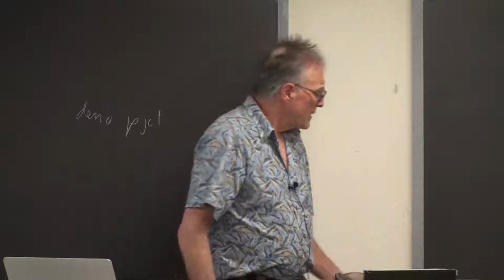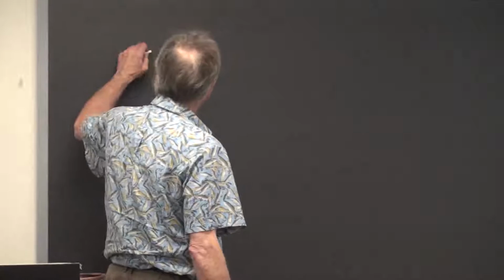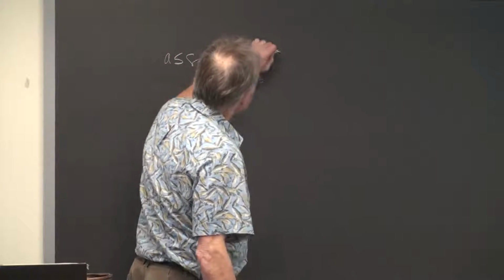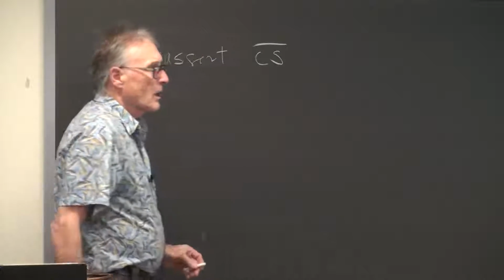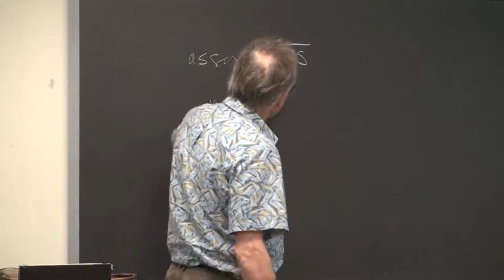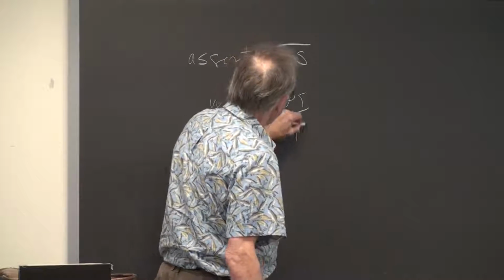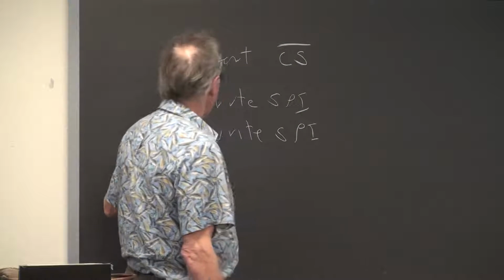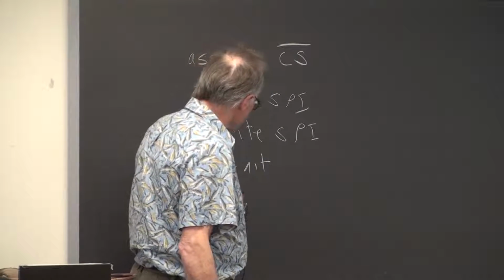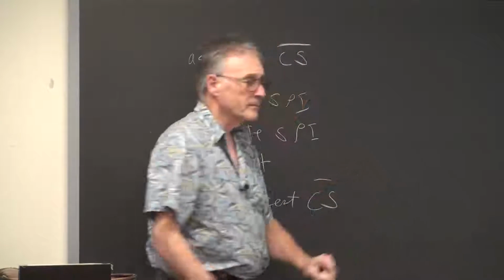Oh yes. So what I saw one group doing was to assert the chip select line, write the SPI, write SPI again, wait, and deassert the chip select line.